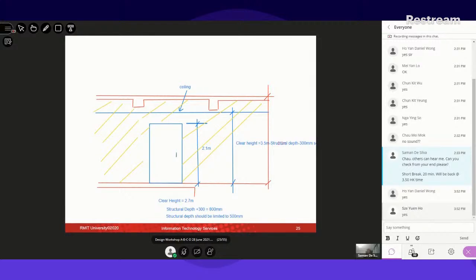So you can see that in this situation, this is the lower level. That is how this elevation is very important for you to know. You now know, okay, you have to work within 500 millimeters of it. Let's say you design and your deepest beam ended up being 600 millimeters. So what? It becomes 2.6 as the clear height. And eventually you have to figure that out. It is important to do that.